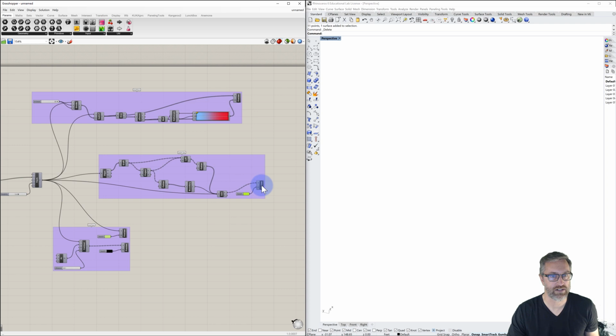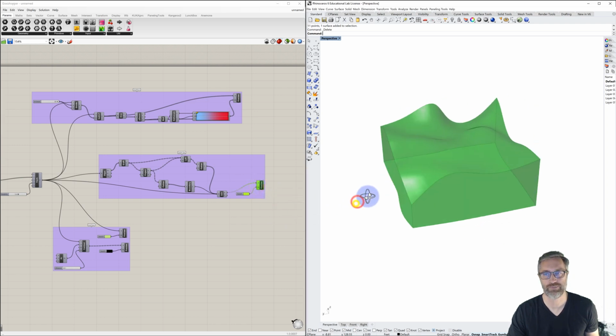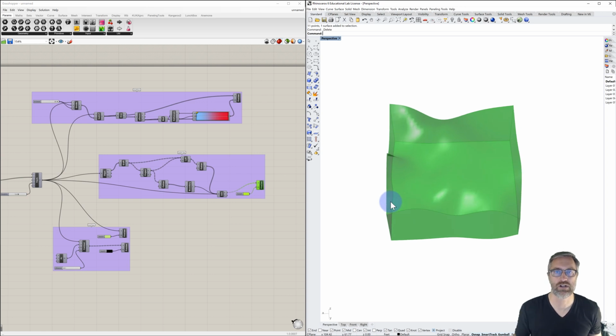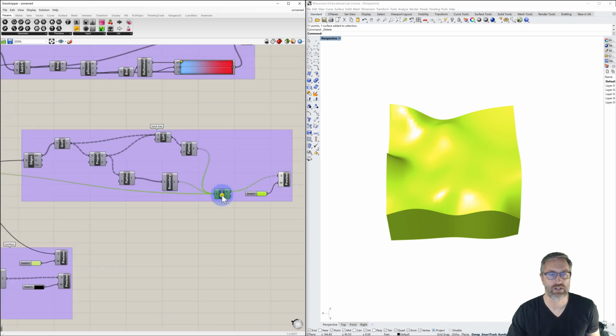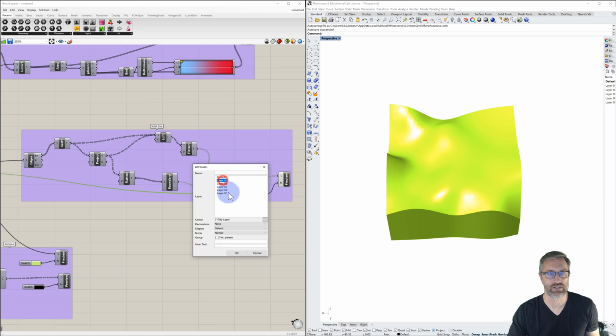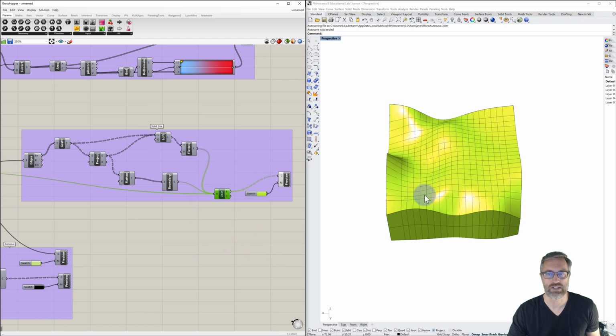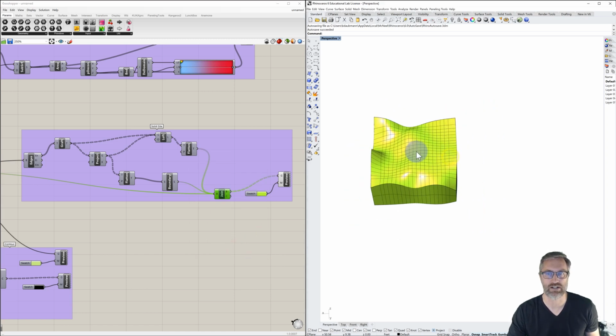We can come back to our solid representation. And if you're going to work back and forth between Rhino and Grasshopper, what we can do is come to the join, right click, and bake this geometry. We'll set it to default layer. Group it, although we shouldn't have to group it because it's one thing. We can see now that this just generated Rhino geometry.